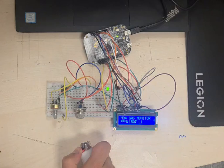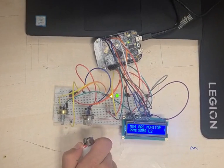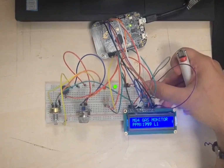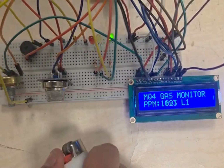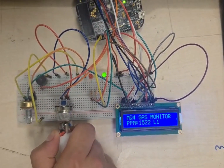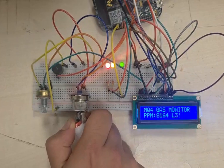The MQ-4 sensor output is continuously read using the ADC module of the KL25Z. The raw ADC value is converted into voltage and then mapped to an estimated ppm value in software. This ppm value is compared against the predefined thresholds. Depending on the result, the corresponding LED is activated. The LCD display is updated, and if the critical level is reached, the buzzer alarm is triggered.